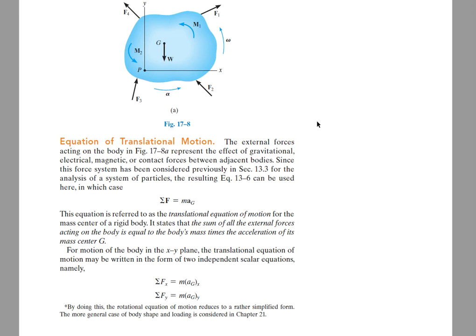It's a concept that is not embraced by the book, but we can talk about inertia forces collecting at the same center of mass. So the conclusion is that the sum of forces that you see here acting causes the center of mass to accelerate according to Newton's second law. So again, there's no rotational effect. Alpha is 0. These moments cancel each other, or they are missing, and the body is just translating. And Newton's second law applies for the center of mass of the body.